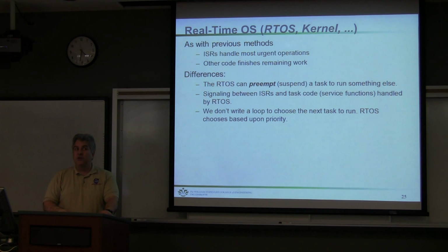The assumption when you build a real-time operating system and an embedded system using it is that each individual task does not take a lot of time. The example that we showed from the book and in our little exercise was taking way too long. So if we had done that again, where each timer tick was maybe 2 milliseconds, and everything could run in that time no problem, that would probably be more of an appropriate example of a real system.